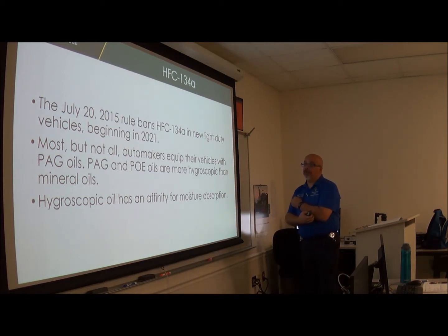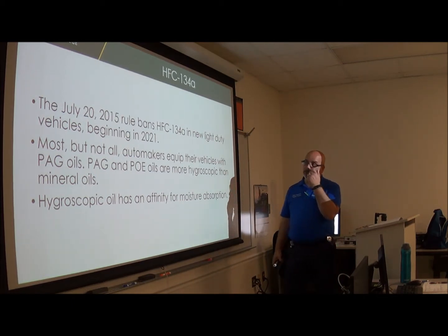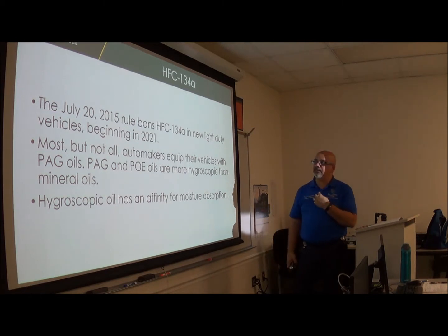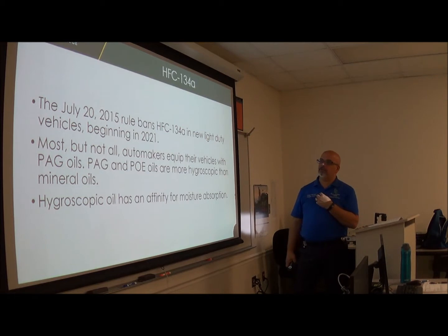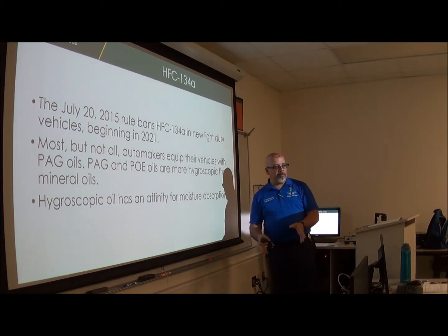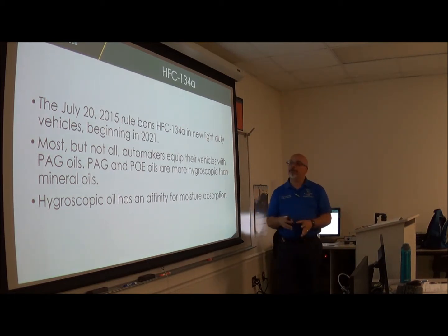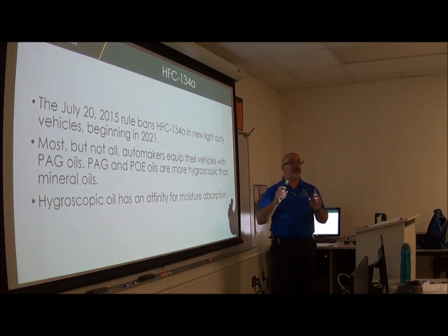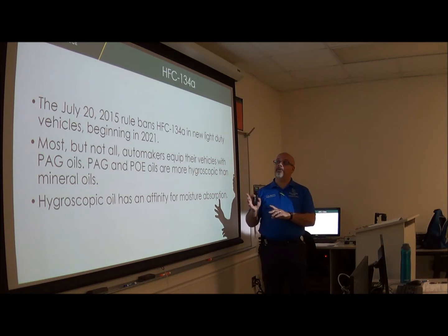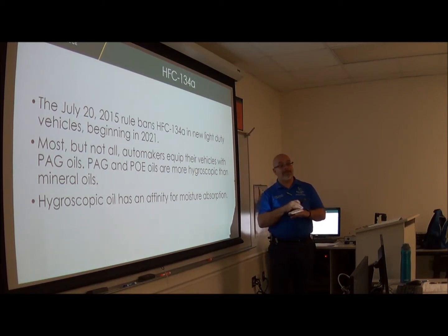HFC 134A: the July 20, 2015 rule bans HFC 134A in new light-duty vehicles beginning in 2021. Remember I mentioned a little while ago that by 2021, every light-duty vehicle cannot have 134A.